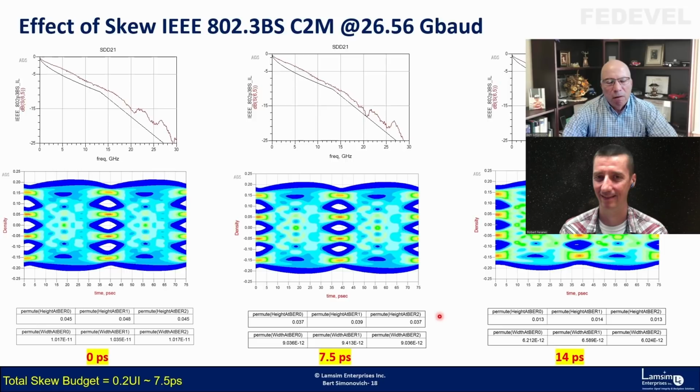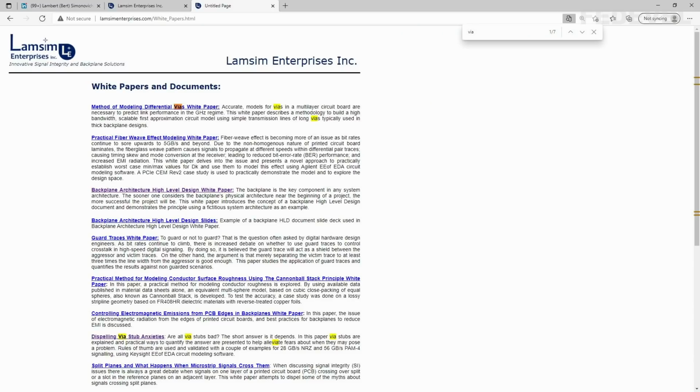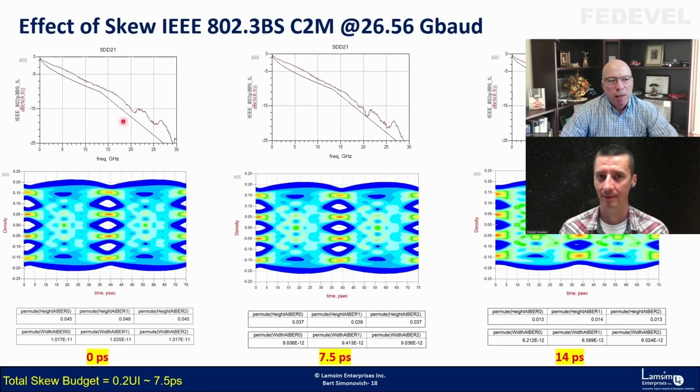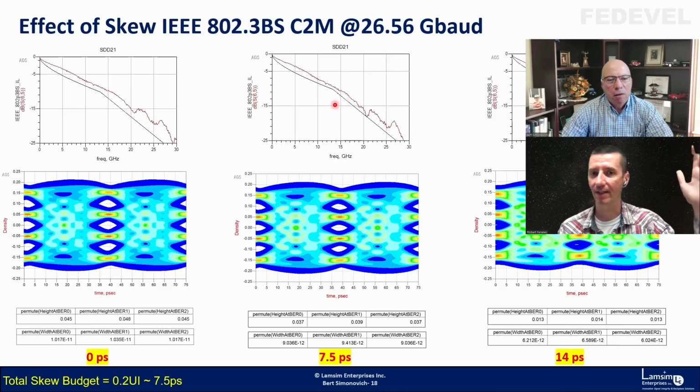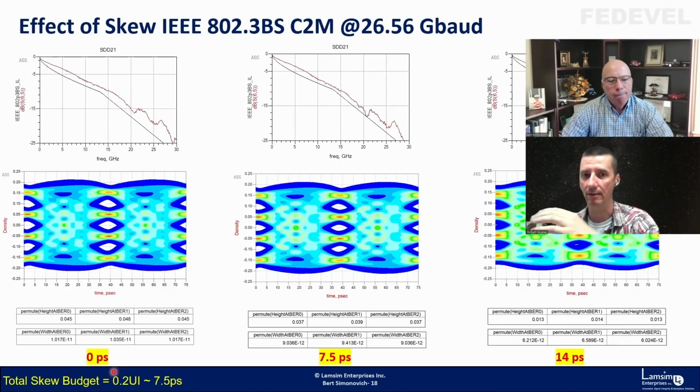I go into the things in more detail with the via stub resonance in one of the white papers on my website. It goes into that theory, but it's all connected, right? So, resonance, that's why we want that first dip resonance to be 5 times away from your Nyquist, because it affects basically the whole line.